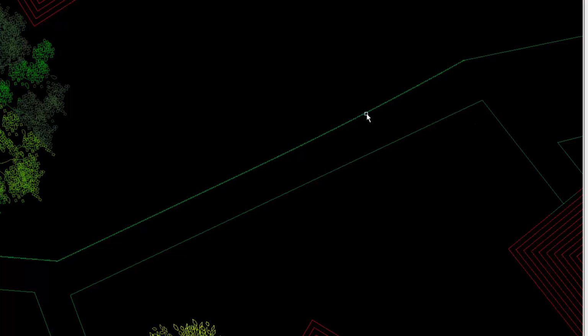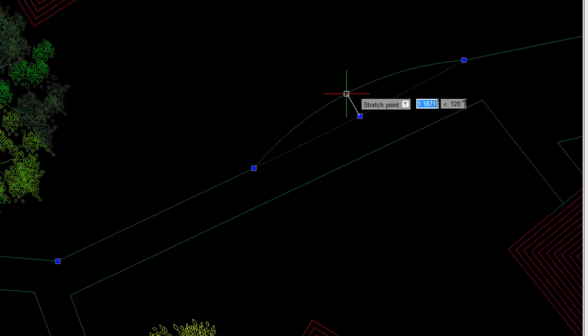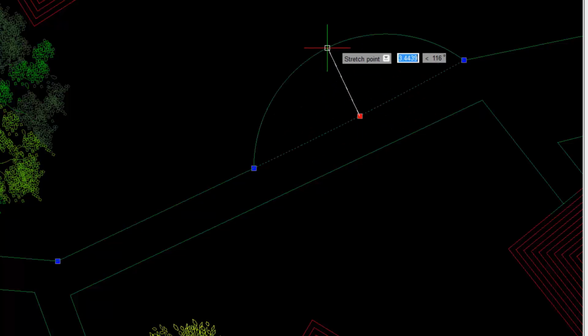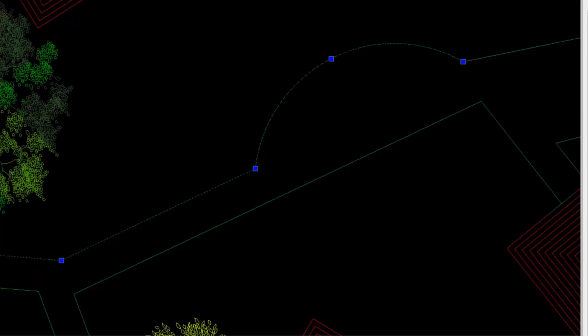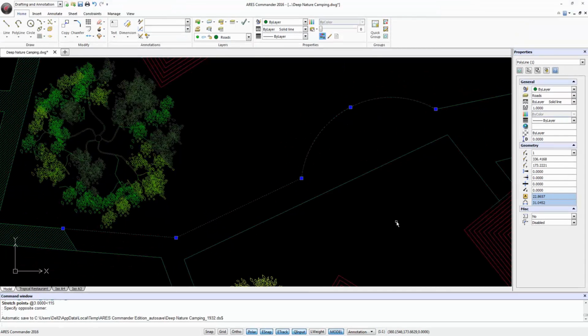When selecting the polyline, grips will show which allow to edit also the arc that we created within the polyline. In the pointer, we can directly modify the values of the arc by using the Tab key to jump to the next box. Moreover, with this polyline being selected, we can position the pointer on one of its vertices for temporary dimensions.